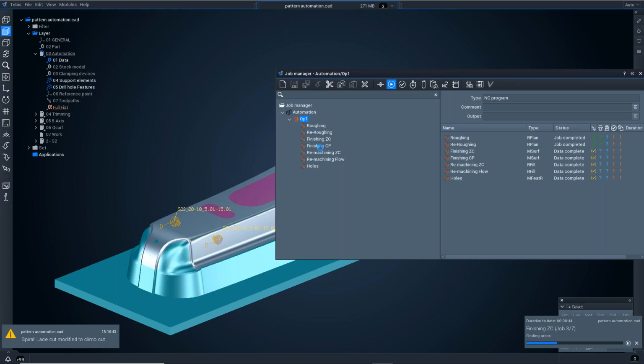So as we come down then, we've got our steep areas finishing. So this will be surface cutting down the steep areas of the component. We then have the shallow areas machining, which will be coming up next. And this covers the large surface areas, all in the predominantly shallow areas. The next two areas down then are residual fillet machining.